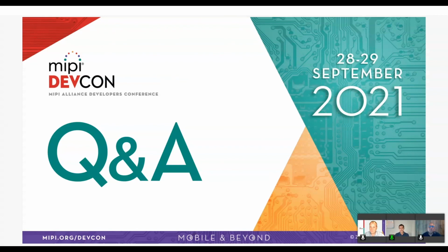And also, in advanced FinFET nodes, something that we touched on in this presentation, these chips are definitely being targeted for really advanced FinFET nodes. So a C-PHY, D-PHY combo implementation in an advanced FinFET node is what I'm seeing from where I'm sitting. Yeah, just to add one thing, I completely agree, and this is also about flexibility of design and future proofing. This is one of the reasons that in the Valens product, the VA7044 deserializer, there is a combo of C-PHY and D-PHY, exactly for that reason.